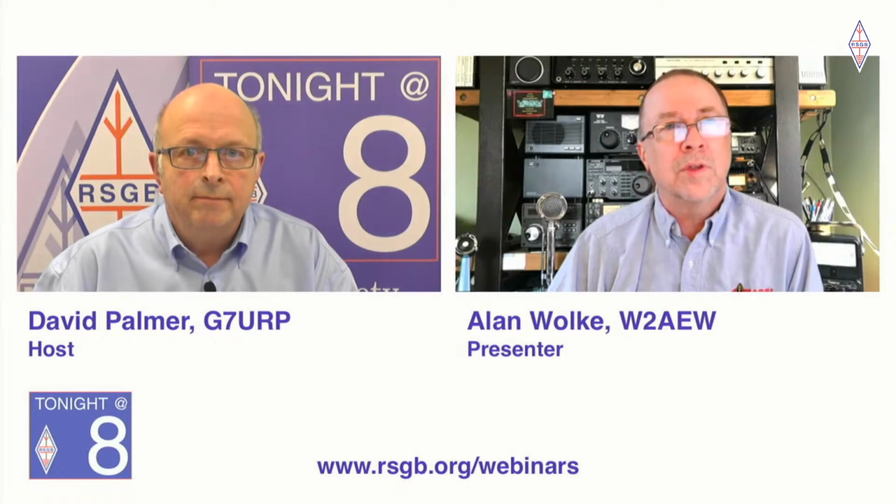Any workarounds for that? Well, the calibration kit that typically comes with these things is typically an open, short, and load. The open and short are pretty basic. The quality of the load in terms of how accurately it's 50 ohms and how good of a 50 ohm resistor it is over broadband will tend to vary. Oftentimes they're not really the greatest things. And compared to, say, a professional calibration kit will often have additional terms associated with an open, load, and short.